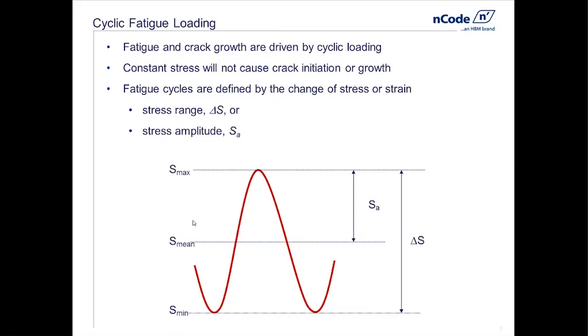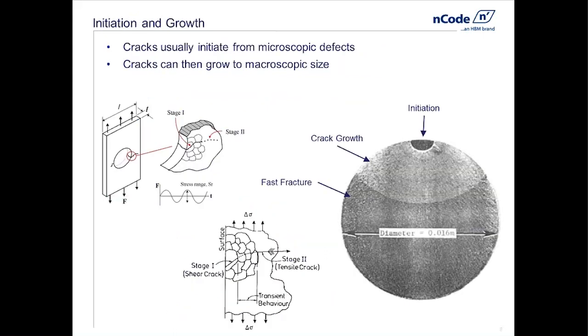All right, so that's a cycle. So think about what stress cycles actually do. Stress cycles or strain cycles can cause cracks to start, and they can cause cracks to grow. So let's think about what this means. Cracks usually start at microscopic defects.